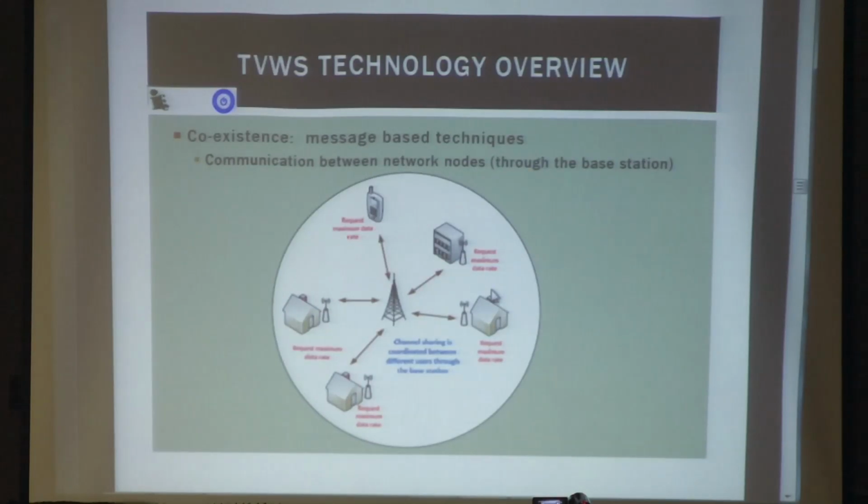And I guess the most elaborate one is called the message-based techniques, where you have two-way communication between the TVWS devices and the base stations. The TVWS device says, I'd like some sort of bandwidth, and the base station gets the requests first from all the TVWS devices. Then it tells each TVWS device, you can get this bandwidth. So there's some cooperation between the different TVWS devices, but it's done through the base station itself.